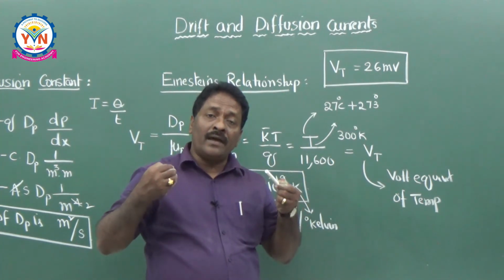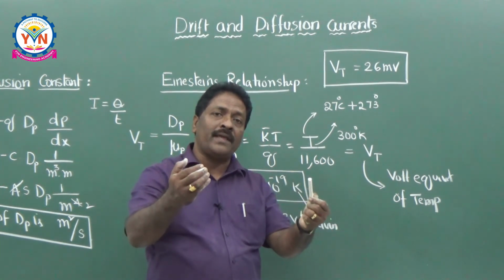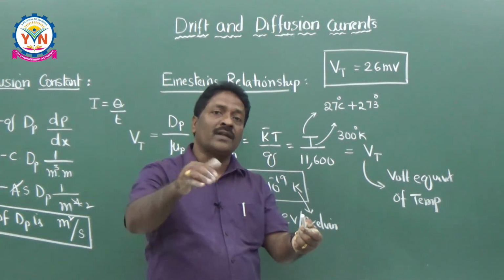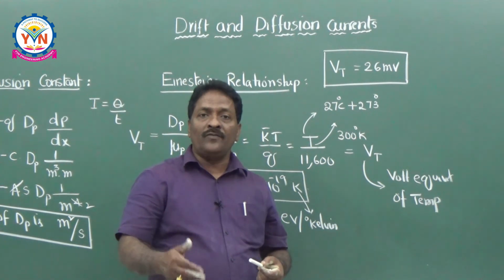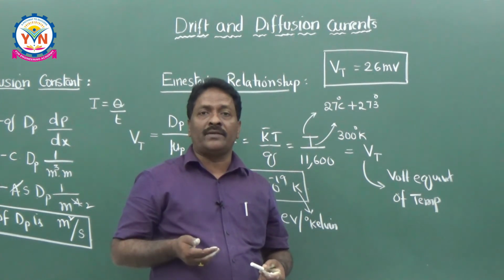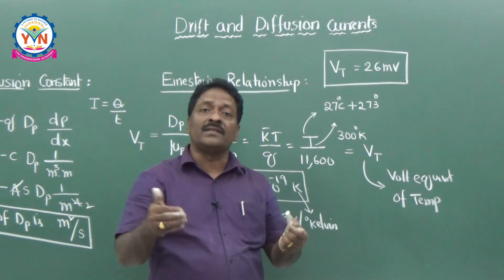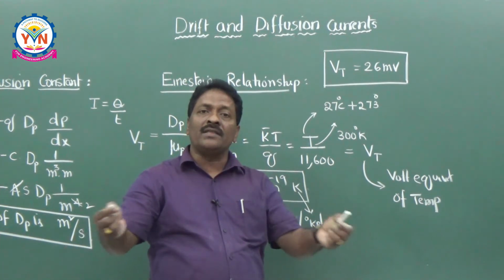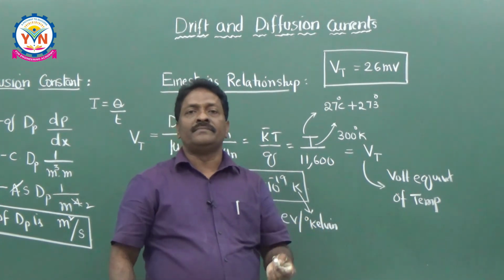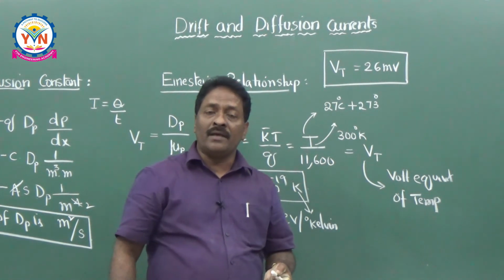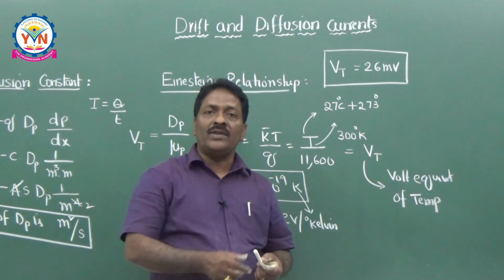And if the voltage is applied externally, that means if you apply it from outside, then also a current exists, and that current is called drift current. So in future, whenever we discuss a diode, initially it will have a diffusion current whenever the voltage is not applied. Whenever the voltage is applied, it will have two types of current, diffusion as well as drift. That's why the current in a diode will be the sum of diffusion current as well as drift current. I think you understood this.